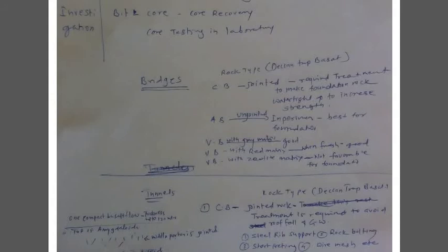Then prepare a geological map there, collect samples, and mark the junctions and any geological feature like dike or fault, and you will have one contour geological map as it was given in your practical in semester 3. From that contour geological map, construct 3, 4, 5 geological sections and select out of them the best. Select that alignment.